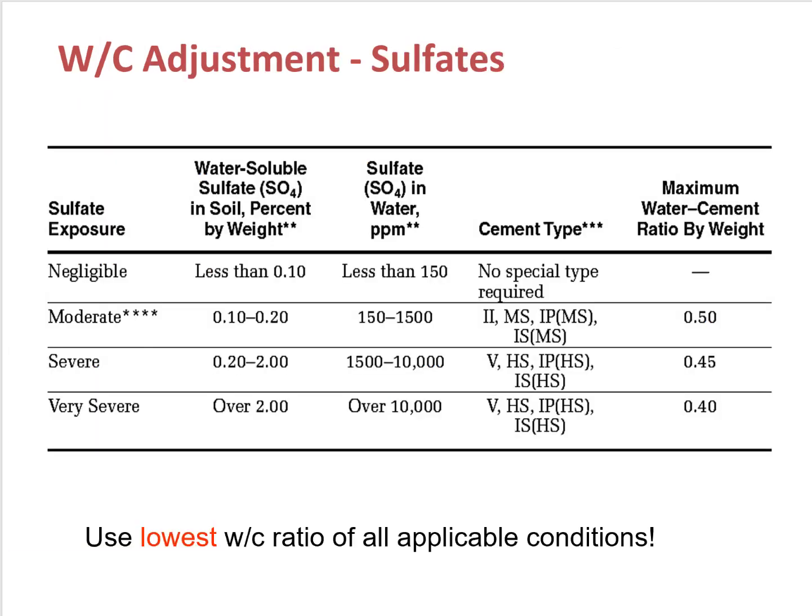And if the concrete will be exposed to very severe sulfate exposure, then the water to cement ratio should be further lowered to 0.4.